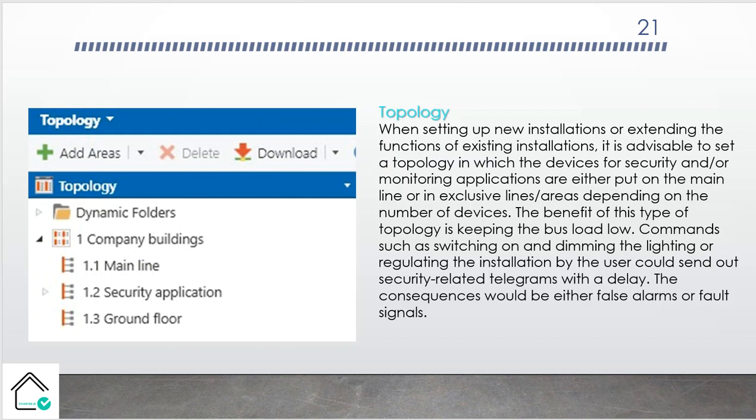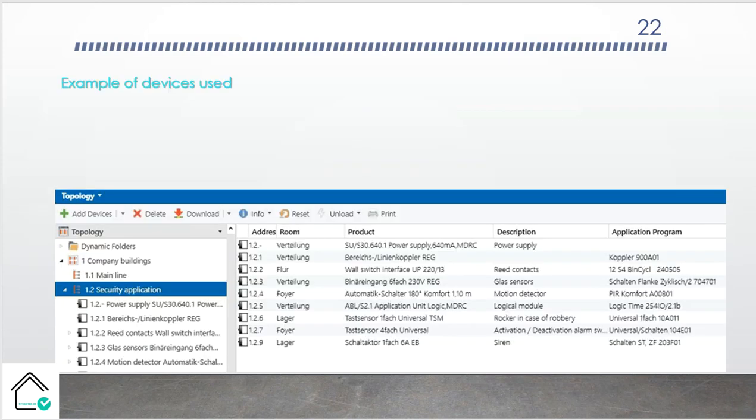So you never, or almost never, lose the telegram or packet of data in the security line. So it is highly recommended to have the extra line with the line coupler or IP router for the security systems in KNX, if you have it, of course. So you never lose the data and the false alarm is eliminated.